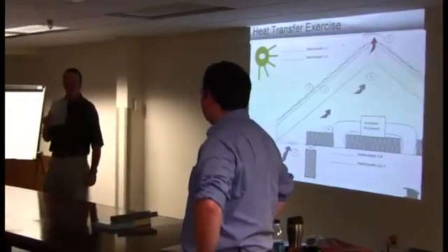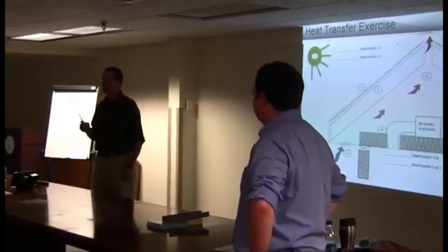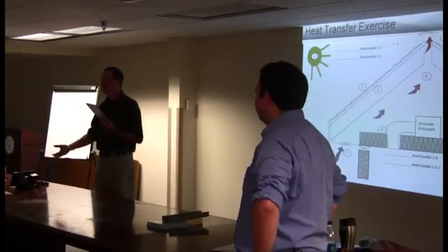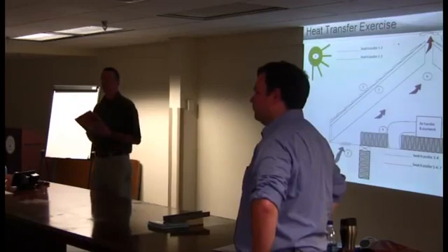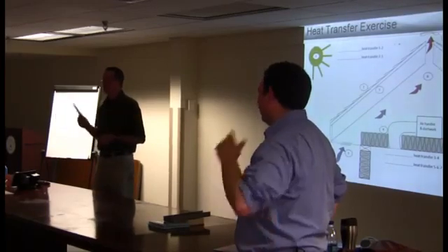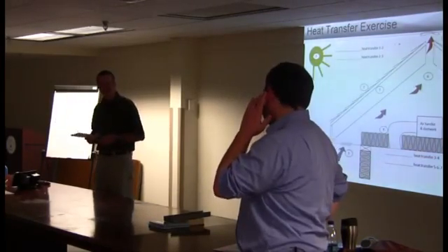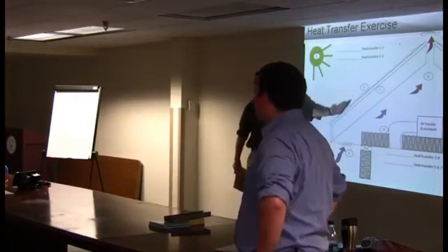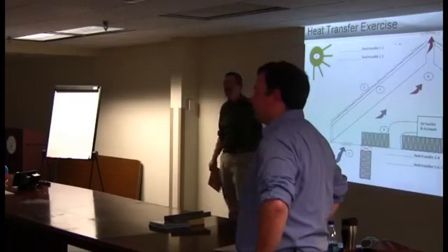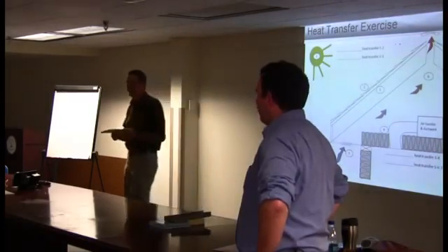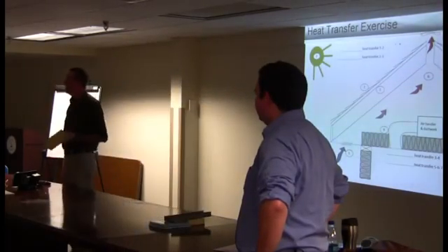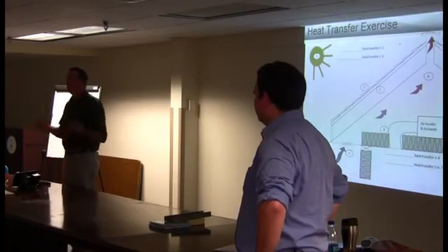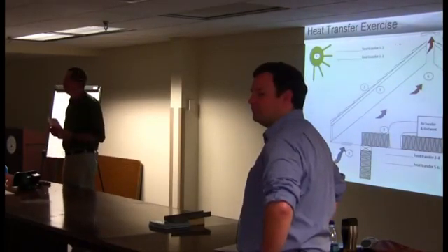I don't know that it will gain you any credit per se in terms of the energy code. It would actually potentially downsize your equipment, and it will offer some energy savings. But it's not the same as if you had, in essence, a shiny roof out here. That is given some credit in the code. One of the things I did want to emphasize, though, is we could rethink our whole attic assembly. Instead of a flat ceiling with insulation, what's an option we could do instead?